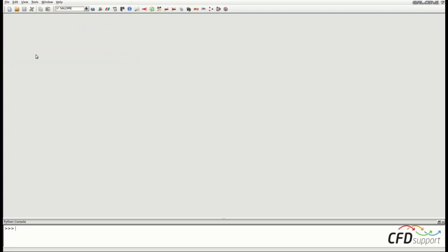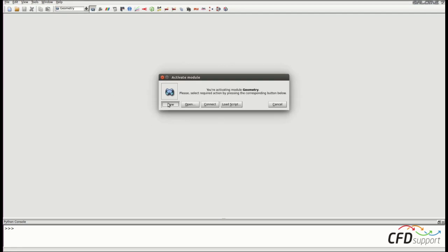This is the first video that belongs to the valve preprocessing tutorial. In this video we will load the geometry and extract just the geometry parts that are necessary for the CFD simulation. It means just the parts that are in contact with fluid. Let's start by activating the geometry module here and then click New.